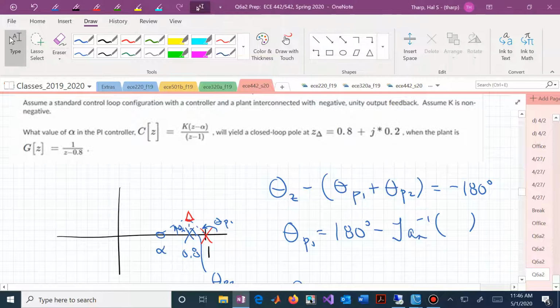Now, really what we're asking is, once somebody tells us where that triangle is, can we actually make the root locus pass through that triangle? This is really a 2 poles to the right of a 0, but we can use the phase angle condition because all of our closed loop poles have to have an angle of minus 180 in order for those points on the complex z-plane to belong to our root locus.